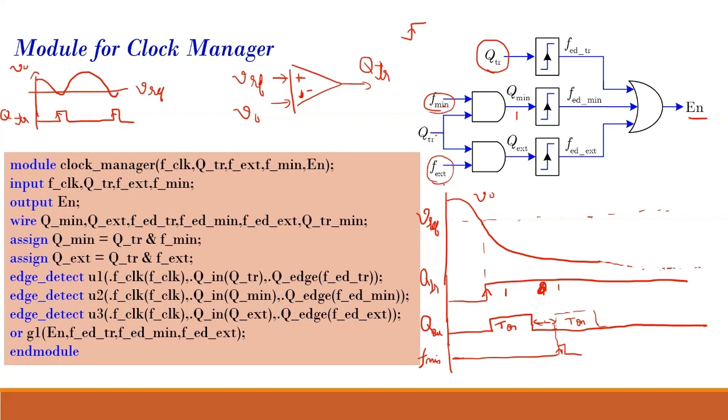Now, F external is another external clock that is coming at switching frequency. You saw FSW has been generated. That is the clock for that. It is an additional safety feature: in case this fails or this fails, and your output is still continuously falling, then this F external is present. Any queries in this?